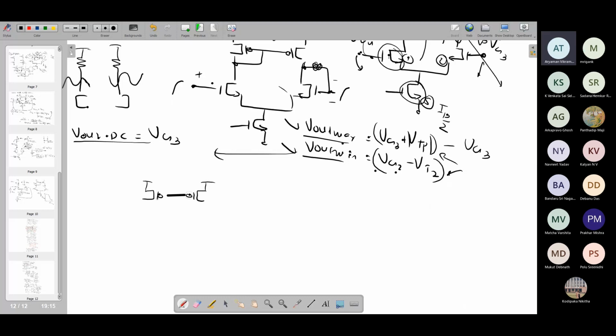So we said differential input and single output. We already have this for the current mirror load. So what is the purpose of putting the second stage? Low output impedance. Like in the last example, we had low output impedance in the second stage. But for an op-amp, we want that, so we have to add the second stage. For the time being, what was the purpose of putting a second stage in the previous case? So that is getting a higher gain.